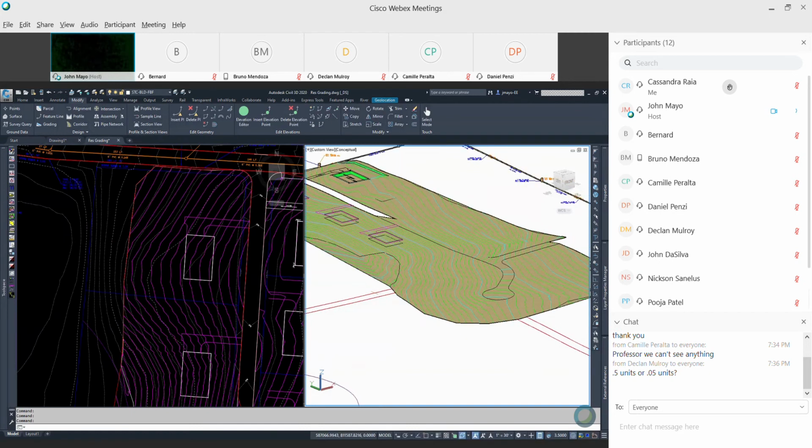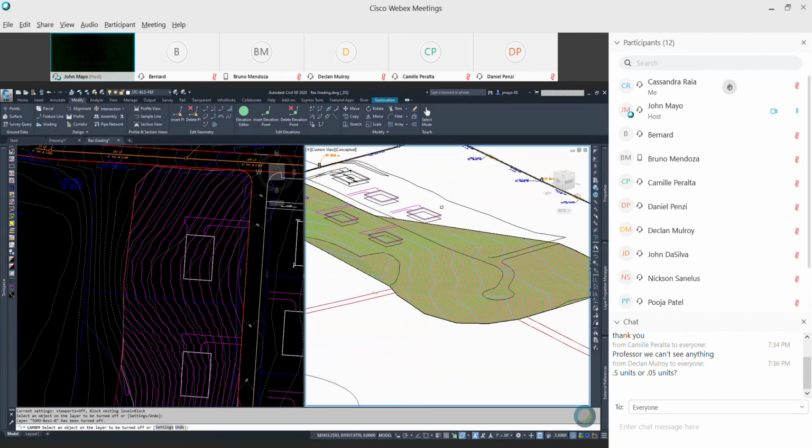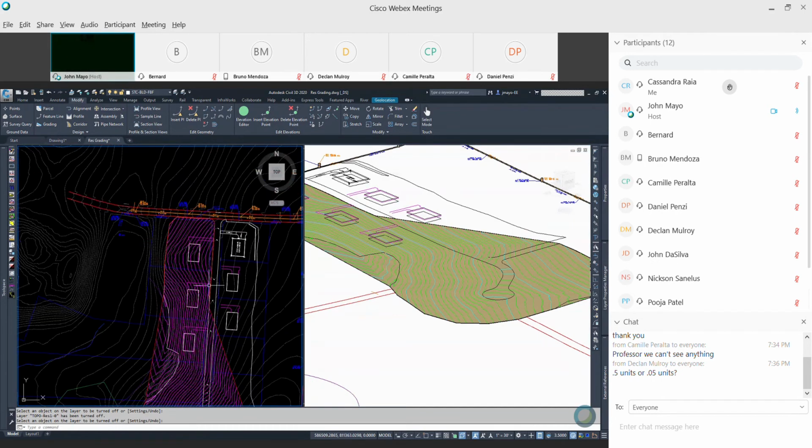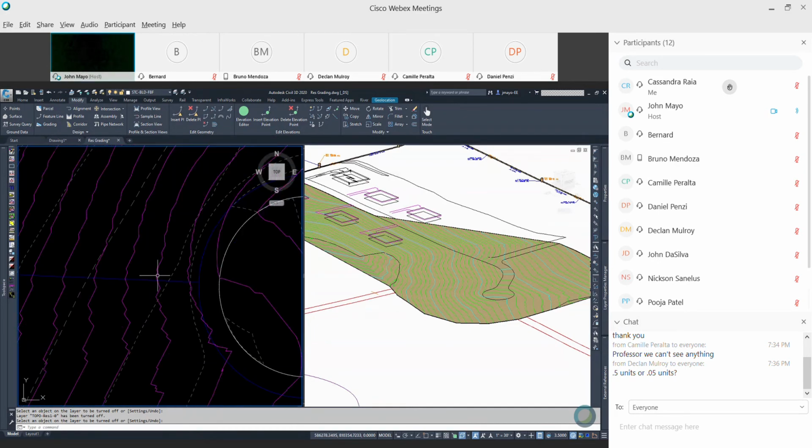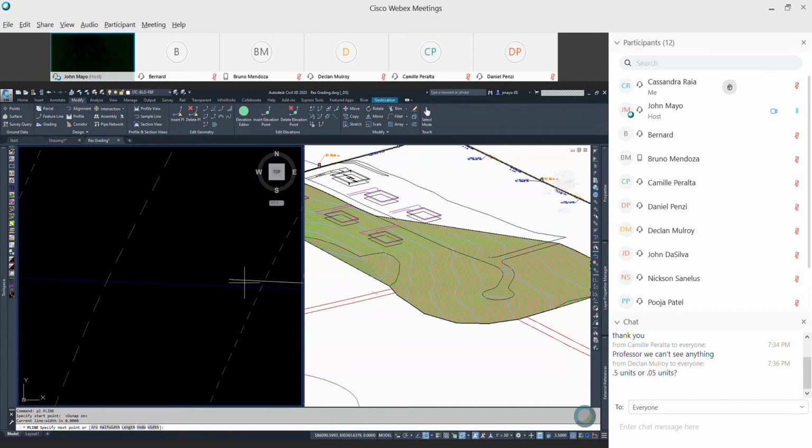Now you note that surface, and I'm going to turn off the other one, is triangulating well outside of our work area, of our limit of disturbance. And that's again because it's coming inside and out of here. And it's also triangulating between the road. What I recommend you do, and it's a lot easier to do it this way, is just divide it into multiple surfaces.